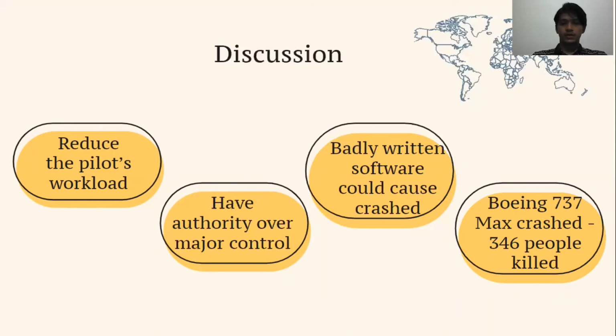Then after 30 seconds, he noticed that there was an alert on the flight display, which means the mission computer detected malfunctioning sensors. After troubleshooting, he realized that the sensors from the left side of the plane were getting bad data.